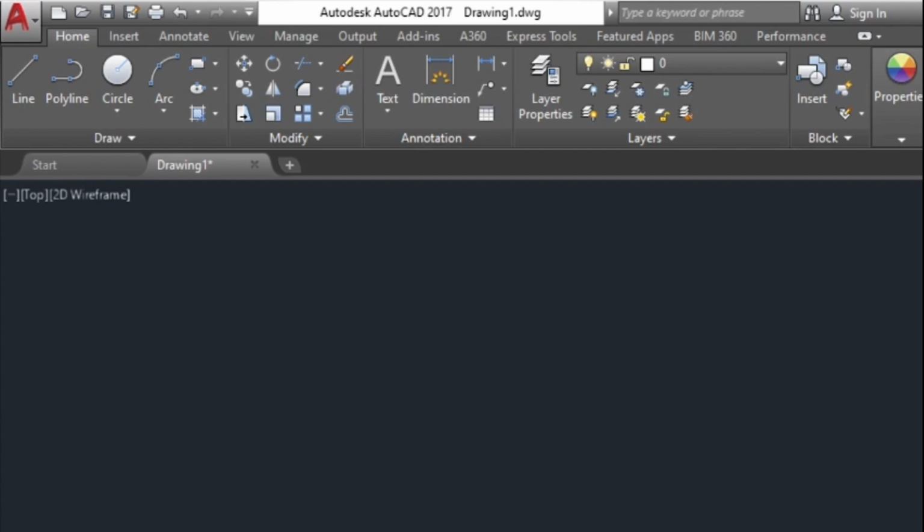Yeah. We have other tools too here. We have the show order, add scale, annotation scale, and then we have the current view. This is to show how the lines are supposed to display. 1:1 is like, let's say, when I type 300,000, it's 300,000 that is supposed to show here. 1:2 divides the 300,000 by 2, so it will show half of the 300,000.